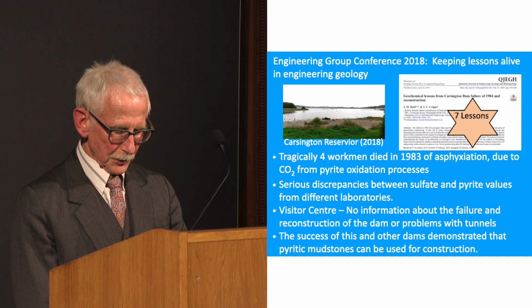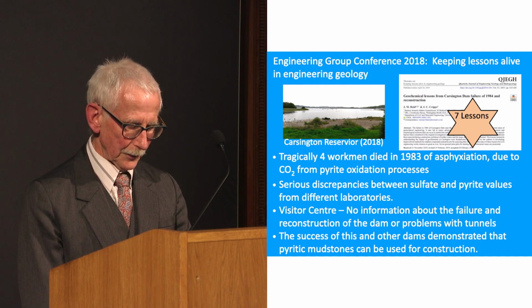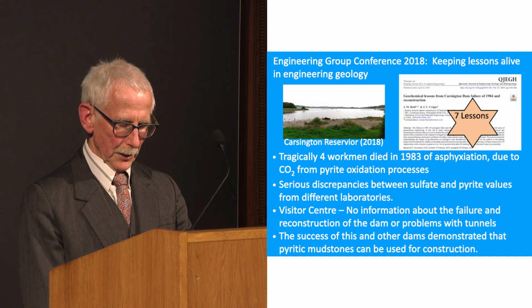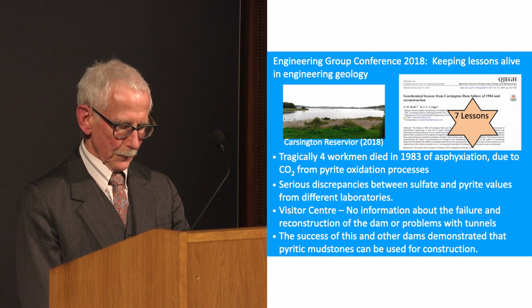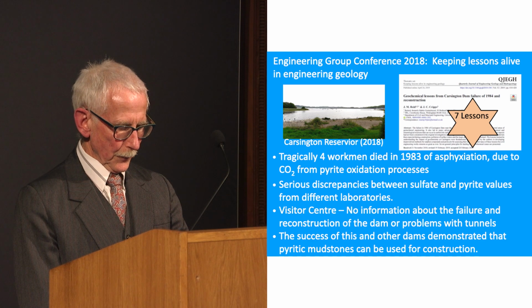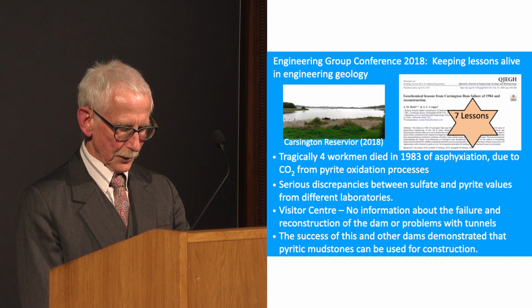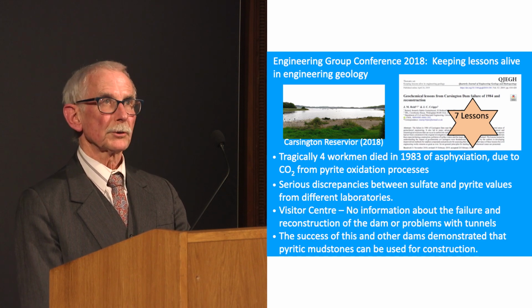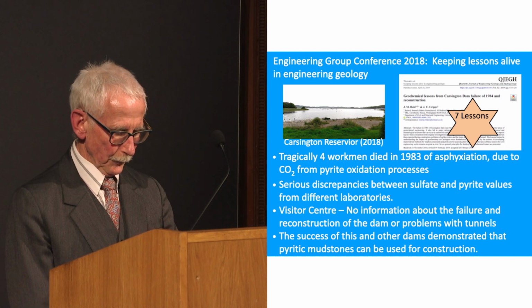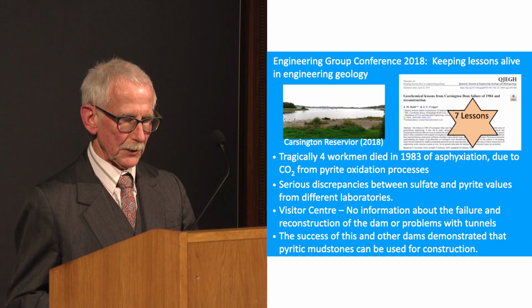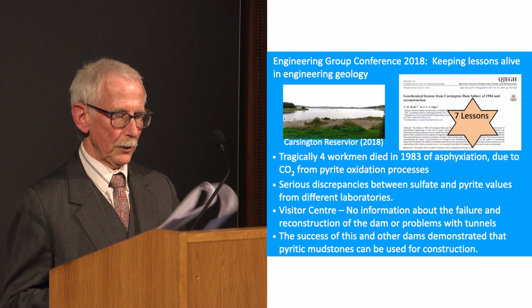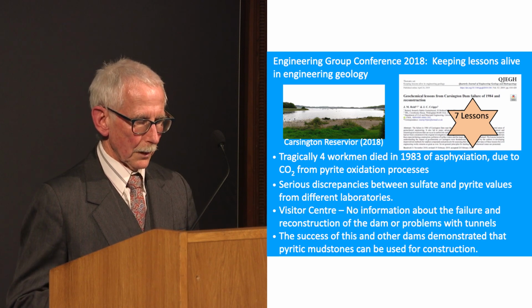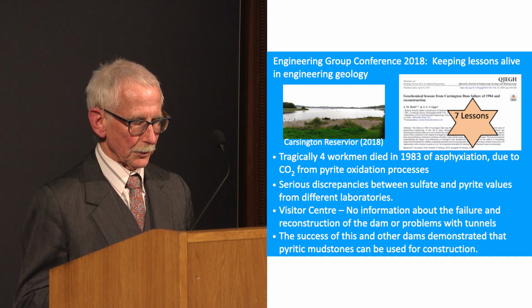We also discovered serious discrepancies in the values of sulfate and sulfide in tests from different laboratories. All were using pretty standard procedures, but there were different preparation and testing methods, and some of them were not suitable for use with a mudstone. Care needs to be taken when using standards that they're going to be appropriate. I'll say more about this at the end of the lecture.